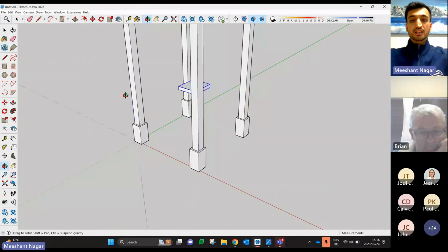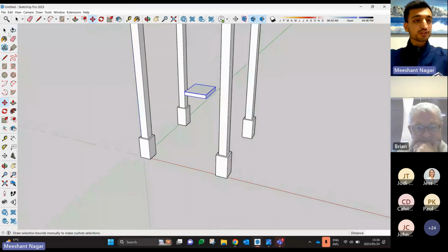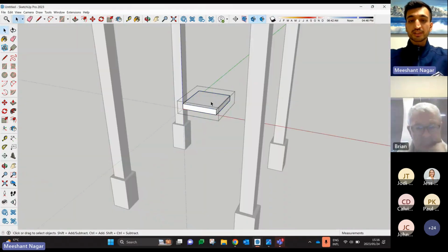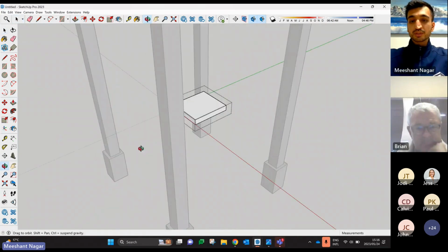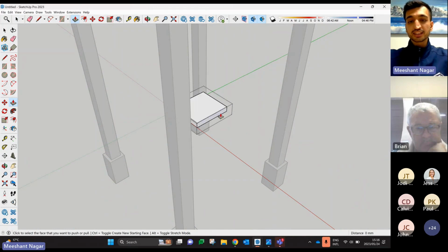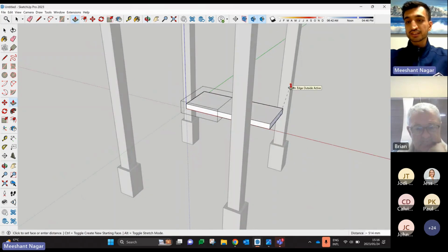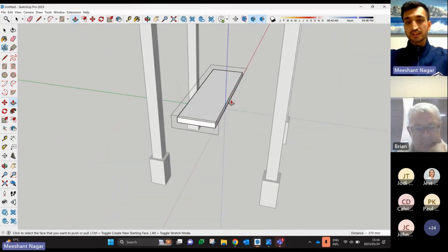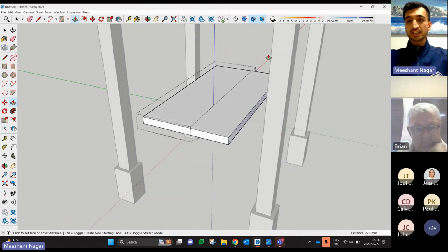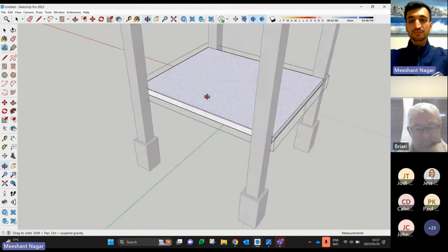So I kind of have it in its right place, but now I obviously wanted to fill up the space. To do that, I'm going to double click the platform to get into the editor mode. And now using again the push pull tool, without knowing the dimensions to the ends, I can easily simply use that face, making sure that the face aligns with the outside edge using inferences. I can do the same with this side, selecting on the outside edge for the inferences. With these sides, I'm going to put them to the inside. There we go. Here to the inside as well.